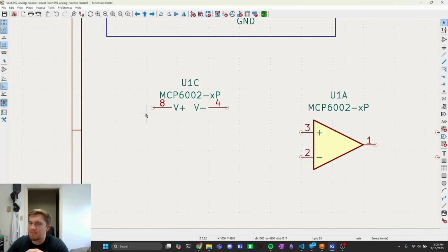We're going to have some filtering going on, probably, I'd guess, in your circuit. I don't know, not to spoil your fun or anything. That's probably what's going to happen. But that's going to be attached to that. So your middle rail, the level your op amp defaults to when there's no signal, will be somewhere between 3.3 volts and ground. To make it super straightforward, sorry, that might have been a little bit confusing, simply do not make the center rail of your op amps ground. Don't do it. You will cry.